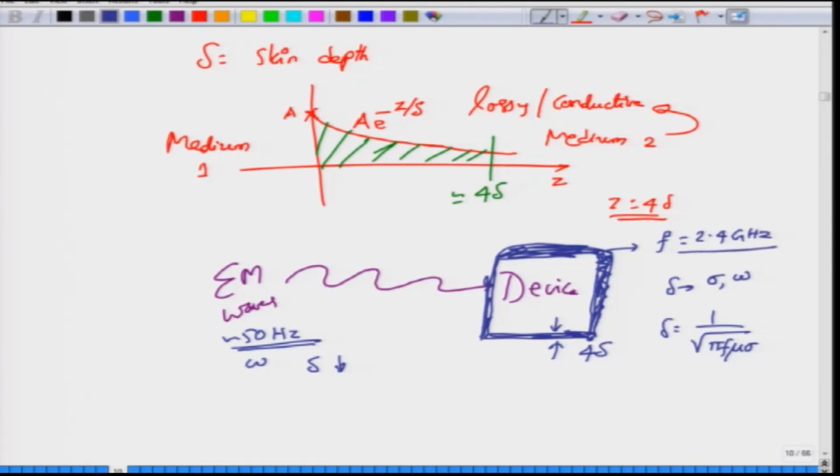So, this idea of what the thickness should be, determined by the material permittivity, the material conductivity and the frequency of operation, the worst case and best case, is not as straightforward as I have written, but this still gives you a basic idea of what to expect when you want to shield certain devices from electromagnetic interference. The concept of skin depth of a material is very important in this case in order to determine the requisite thickness of the material.